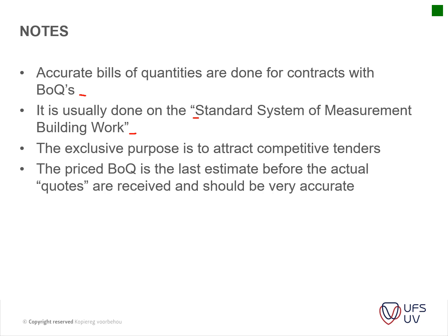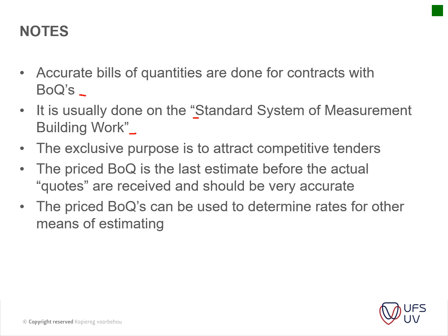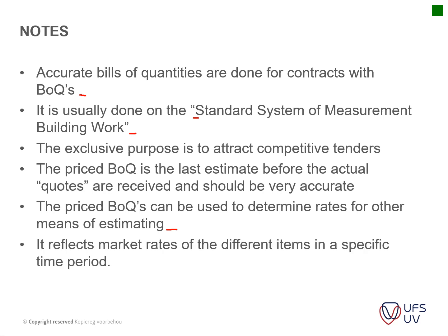Then the priced BOQ is the last estimate before the actual quotes are received, and should be very accurate. Okay, the priced BOQ can be used to determine rates for other means of estimation. So for instance, for your elemental estimate, whenever you've got your bills of quantities with rates priced in them, you've got a lot of nice information that you can use on your elemental estimate again. It reflects market rates of different items in a specific period. Okay, very important.